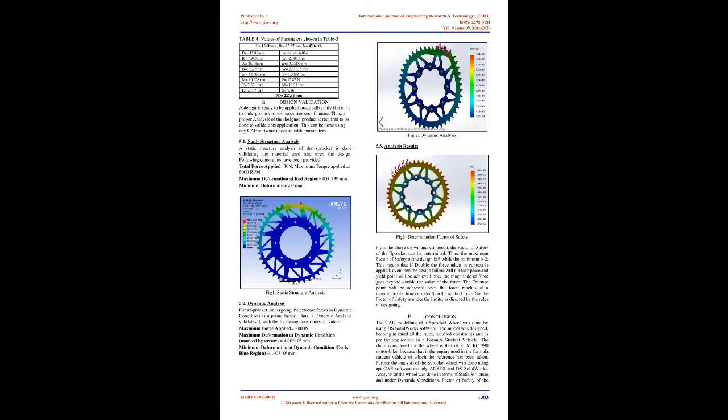1. All the values required were derived as mentioned in Table 3. 2. A pitch circle of radius 1/2 of PD was drawn. 3. Construction line 1,2 was drawn from the center of the circle to the top quadrant. 4. Horizontal line 3,4 was drawn from the top quadrant and a tangent to the pitch circle was made. 5. A circle with radius r was drawn at the intersection of 1,2 and 3,4. 6. Offsetting the above lines was done. 7. Extending line CX was made.